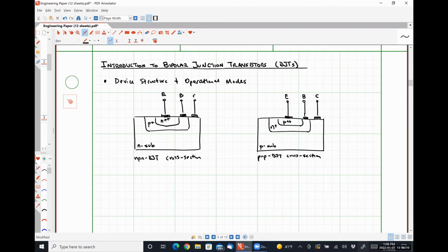And then the emitter is kind of a hot tub in the corner of that pool, if you will, right? So that the area of the base emitter junction is small, or is much smaller than the area of the base collector junction. Okay? Another very key thing about the operation of a BJT is that the width, or effectively the thickness of the base region, we're going to call the effective width, which means the thickness minus the width of the depletion region, which is going to have a depletion region on both sides, needs to be very, very thin, okay?